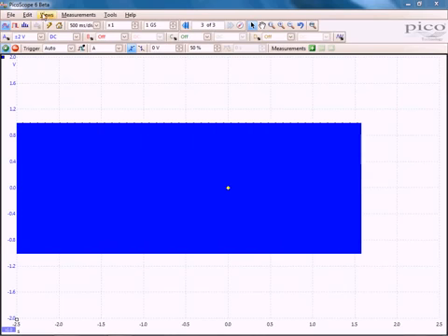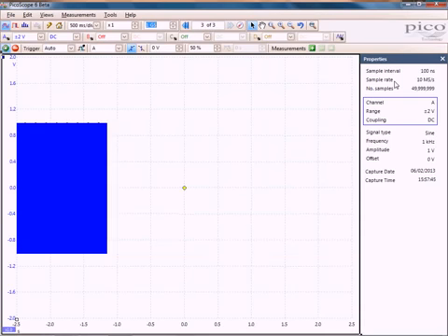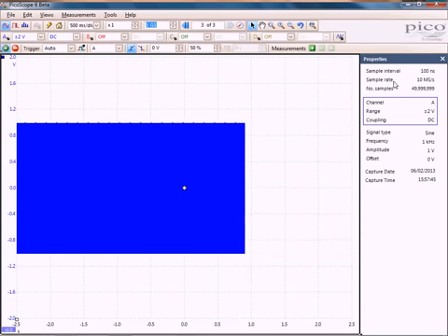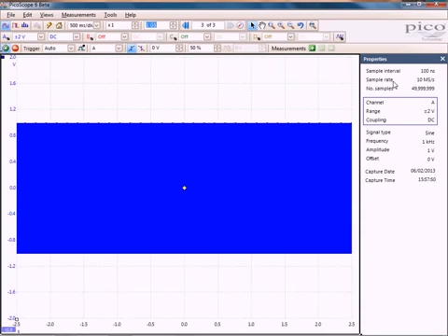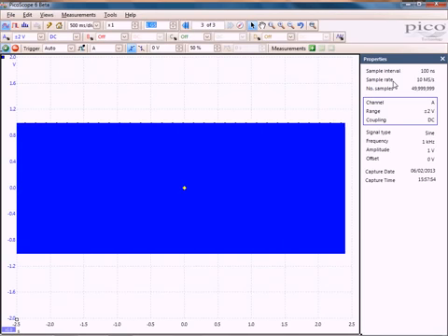To show this, I'll select Views, go into View Properties, and now you can see we have an increased sampling rate in streaming mode of 10 million samples a second. As well as the improved sampling rate, streaming mode uses the PC memory for waveform storage, so it's not limited by the buffer memory of the oscilloscope hardware. A massive 100 million samples can be collected using PicoScope in streaming mode.